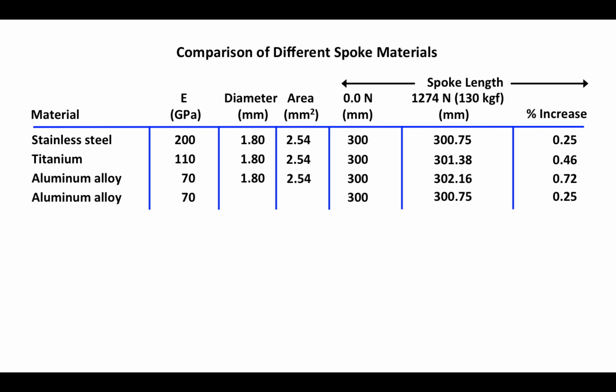When I grind out that calculation, I find that for my aluminum spoke to have the same strain as a stainless steel spoke, its diameter has to be about 3 millimeters with a cross-sectional area of 7.11 square millimeters. If you're talking about high-end wheels that are made for speed, then going from round stainless steel to round aluminum alloy is a bad idea, and here's why.